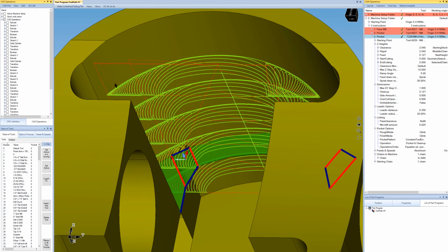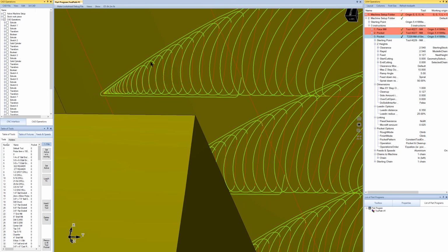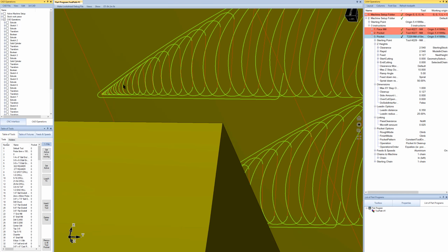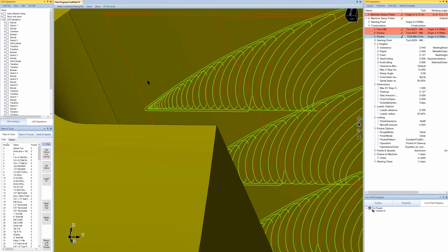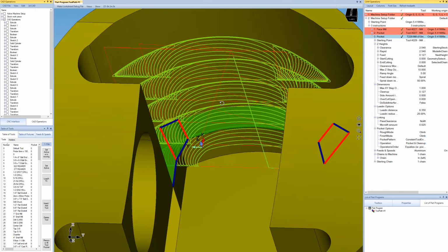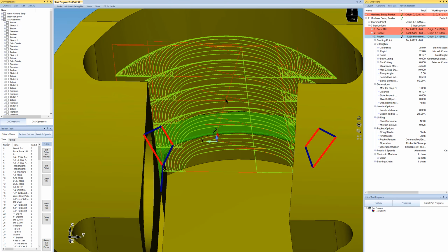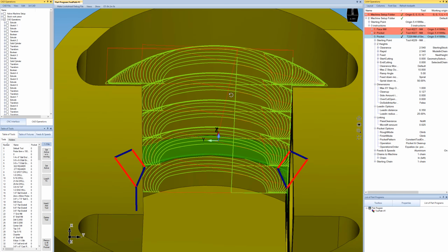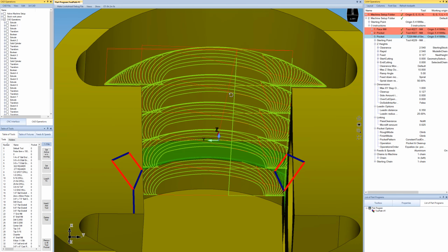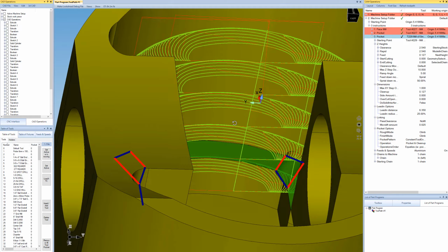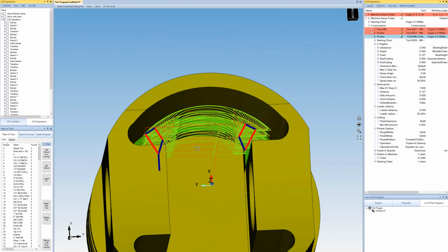So when it goes into corners and things like that, it really changes the shape of the toolpath. In order to get in there, it always takes a consistent amount of material. And this leads to less chirping in the corners and less possibility of breaking the tool, less wear on the tool, and it's just easier on the machine as well. So anytime you can use constant tool engagement, that's recommended. Okay, and I think that pretty much explains what we're trying to do here. Thanks.